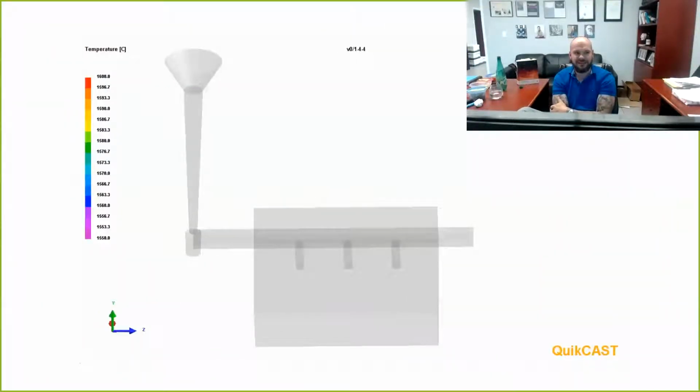The guys that sell us our filters love this because now they end up telling you things like, well, you should really only put 50 pounds of metal through a square inch of filter, blah, blah, blah, all this stuff. Let me tell you that none of that is true. Here I will pour 10,000 pounds of aluminum through 60 PPI filters. There's no slowdown, there's no change, because my filters aren't filtering. I'm using the filter as a throttle, it's only for friction. And if any of your casting systems are using a filter to filter, you've already done everything wrong, right?